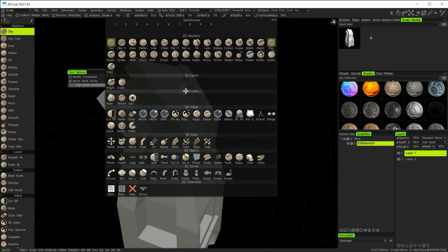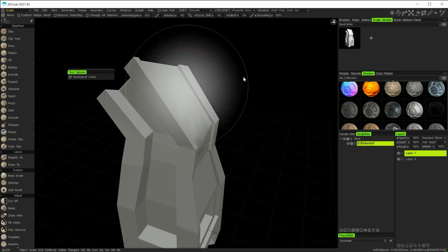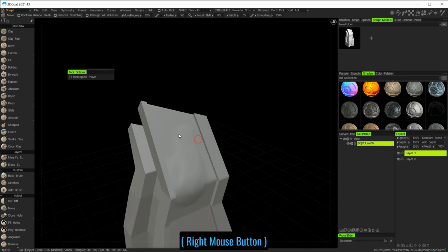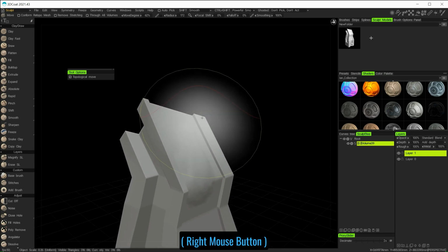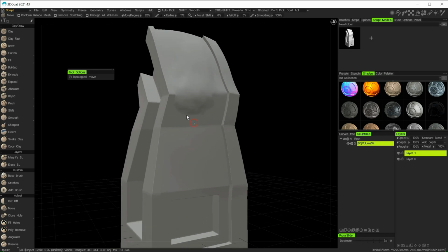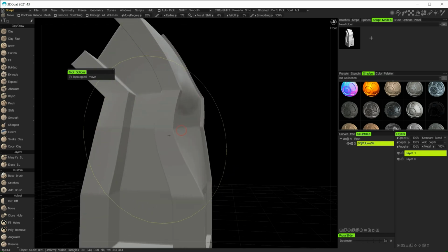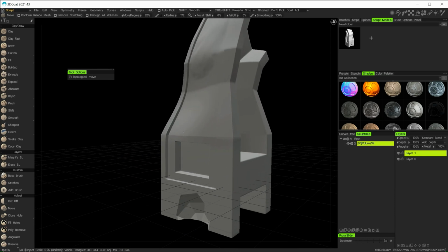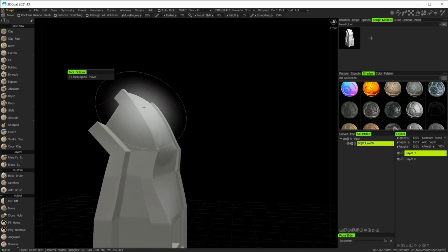Change the tool by hitting spacebar and use a move tool. Increase the size of my brush by hitting the left mouse button, and I can start to sort of pull this shape around. Now, depending on what you want to do with these shapes, obviously if I wanted to sculpt some detail on and then bake that back down to that low poly version that I have in the modeling room, there are ways to conform the mesh in here to the retopo mesh.